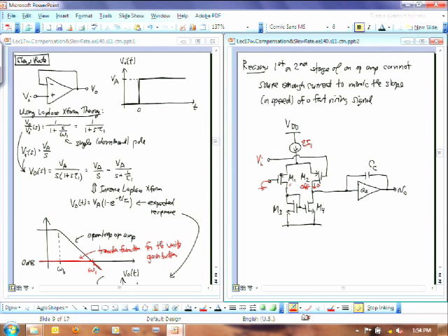That's mirrored current. And then that 2I1 sucking down can suck charge out of that capacitance. But you'll notice that that 2I1, that's all the current we've got. We can't source more than 2I1. There's no way we can do that. This is a current source here. If this is an ideal current source, it only sources 2I1.